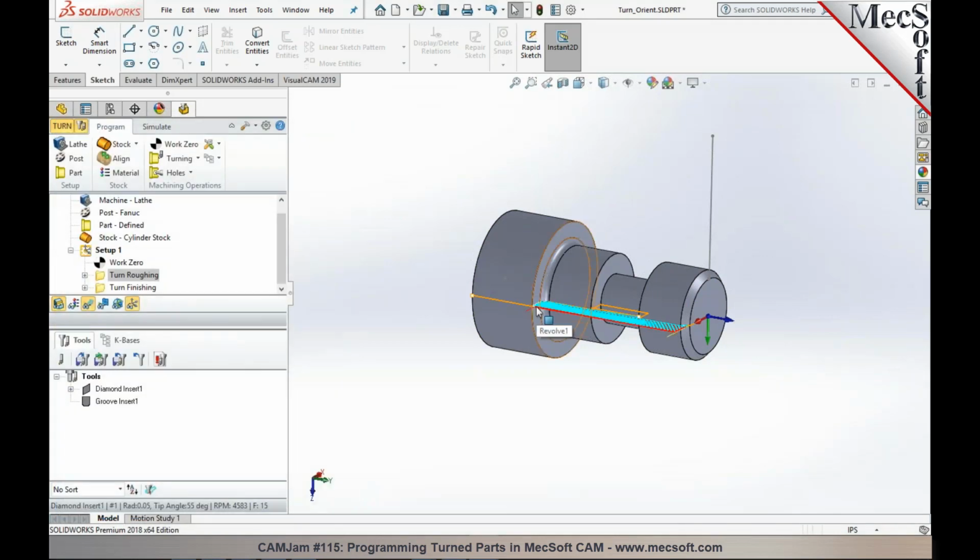So in Visual CAD/CAM and RhinoCAM, you wouldn't have to add or draw these additional sketch or line geometries or curve geometries. However, in SolidWorks, you would have to do that because you wouldn't be able to pick or snap a point out in space.